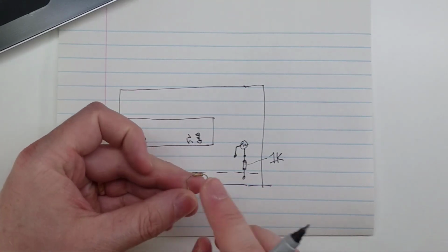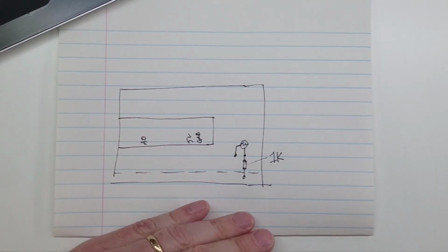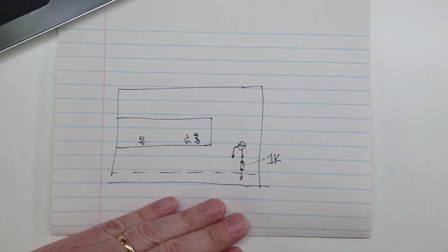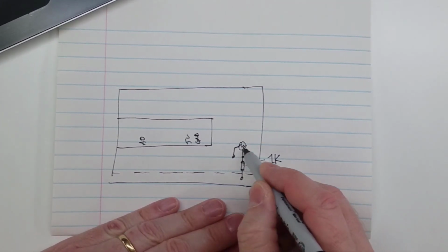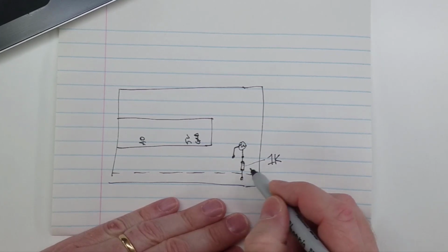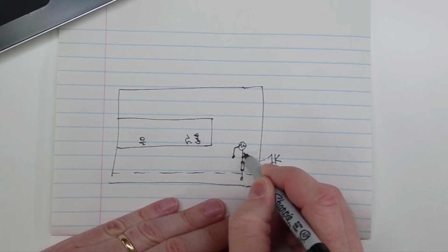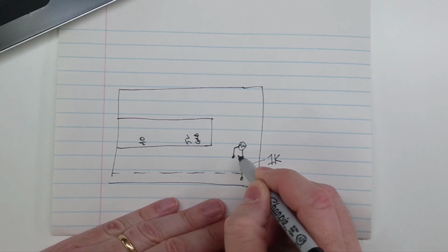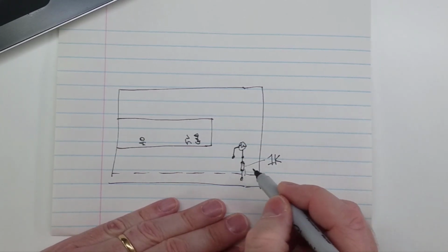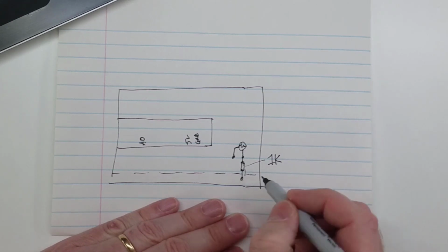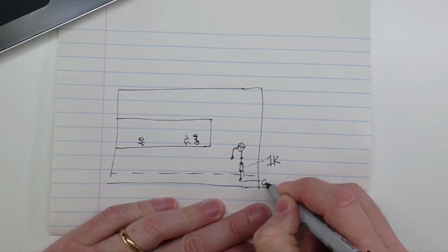This is actually not a 1K, but it's the brown one. It's not the blue one. So you should have a couple brown ones in your kit. So put that 1K in between any one of these pins and ground. And then we're going to also put the photoresistor across two of these. So it'll go one on the left and then one on the right, and make sure it's in the same one as the resistor. Now this is going to be the ground.